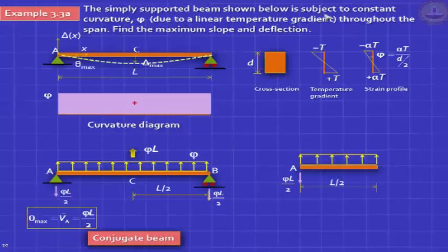And we know that the maximum deflection is at the midspan. So in the conjugate beam, we take a free body at the midspan. And you can see that there is no shear here, which proves that the slope in the middle is 0. But there will be a bending moment here, and that bending moment will be the deflection in your real beam. That's how you do it.